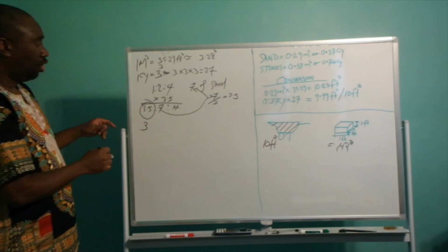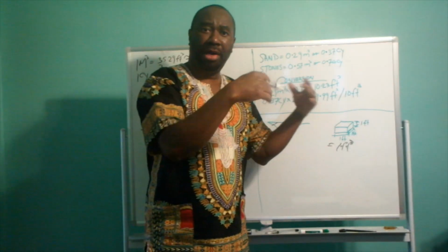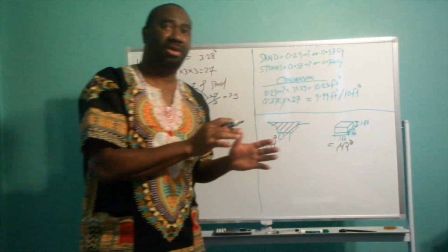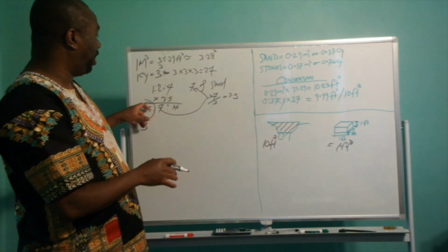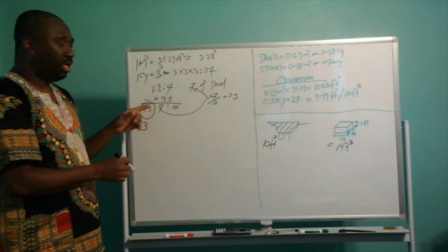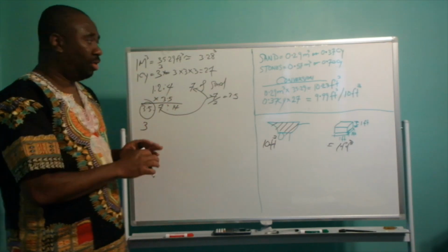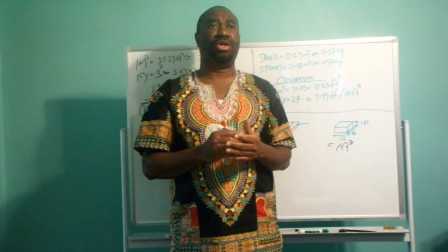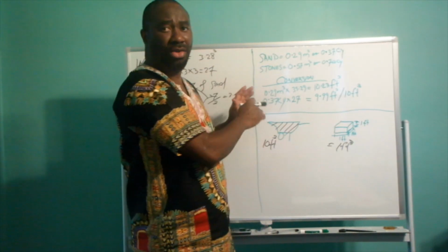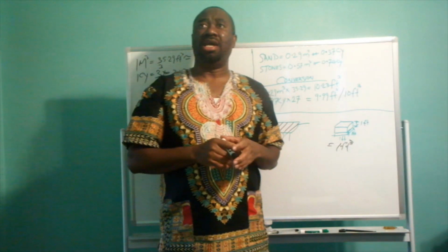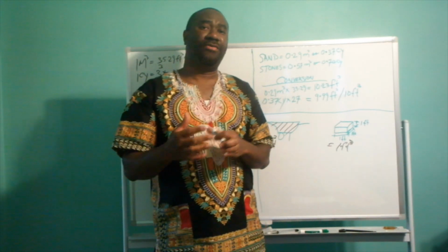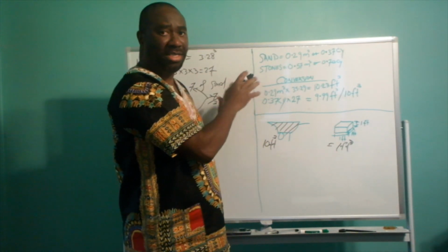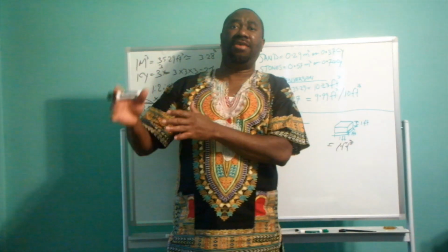So that is why I'm saying do not arbitrarily run on any number, because if you have not factored your mix, you have to come up with the multiplying factor to make sure that your 1:2:4 is consistent with a particular factor, right? So that is it for this video, and the reason why I've taken you through this exercise is to make your material for your mix optimum in terms of cost. And when you can work out your material for your concrete mix, it saves you time and money.